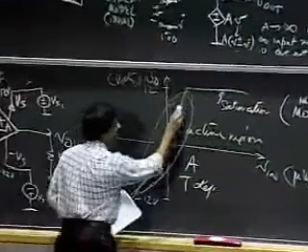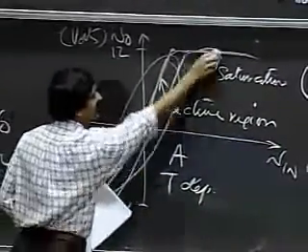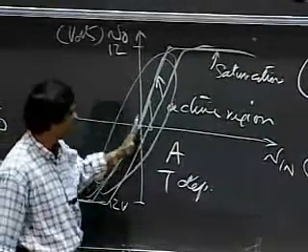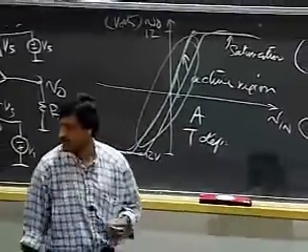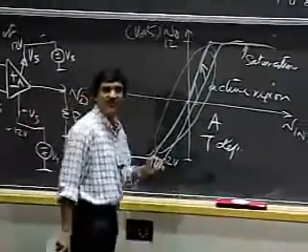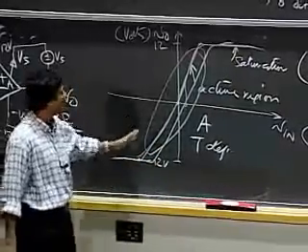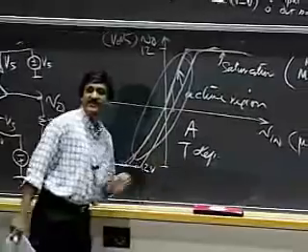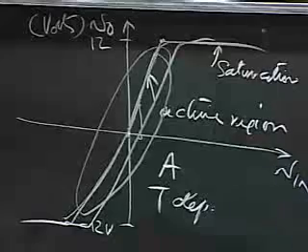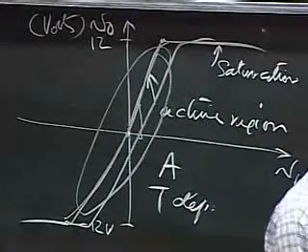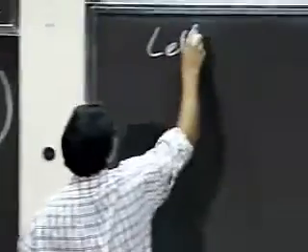So what you saw there was that the op-amp began to behave really weirdly as I heated it. Instead of doing this, it sometimes did this. It did really weird things, such as getting an offset from the center, and it does a bunch of other weird things, but we won't go into those details. It's not relevant for this course. But the point is that the gain and the offset at the input are dependent on temperature. And we'll look for ways to make it less dependent on temperature. So as the next step, what I'd like to do is build a circuit.